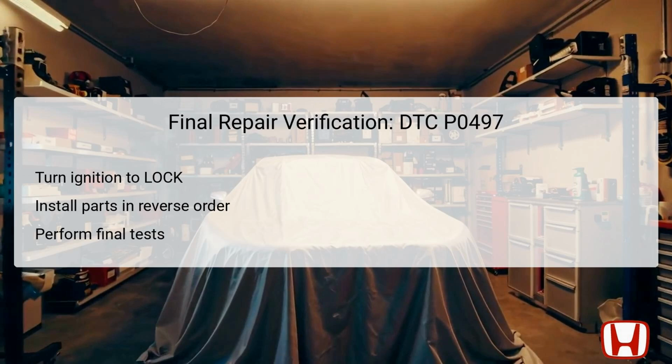Lastly, perform the PCM idle learn procedure to ensure the engine runs optimally following repairs. To conclude the verification, select the EVAP test in the inspection menu and conduct a final function test with the HDS, confirming whether the results are satisfactory. If the DTC remains cleared, the troubleshooting process is successfully complete.